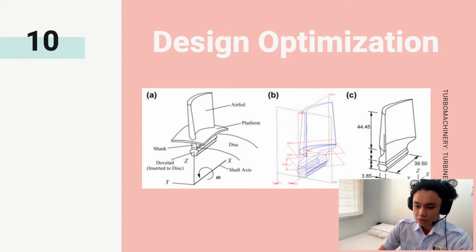When the turbine is operating, air pressure is applied to the surface of the airfoil, and an inertia body force is applied to the whole blade structure due to the rotation. The inertia body force contributes significantly to the blade structural deformation. To simplify the problem, fluid pressure is neglected in the finite element and sensitivity analysis.